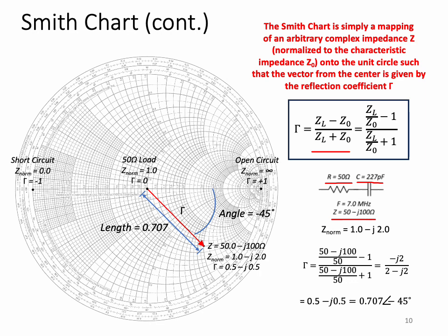Let's now define a normalized impedance equal to Z over Z naught, as it showed up over here. Then Z over Z naught gives us the normalized impedance 1.0 minus j2.0, which will now map onto this unit circle. We can plot it on the Smith chart using the contours that are shown here. Each contour is labeled to allow you to pinpoint a point on the circle.